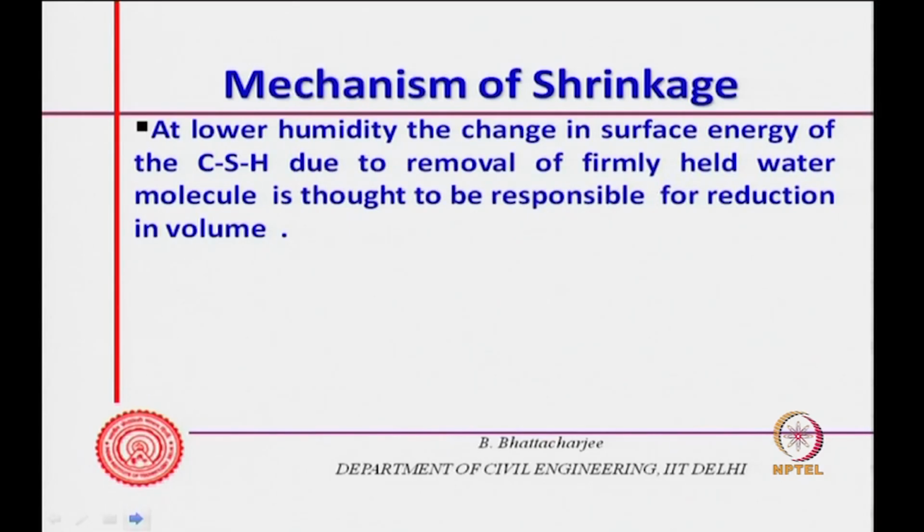At lower humidity, of course, change in surface energy of the CSH due to removal of firmly adsorbed water molecules is thought to be responsible for reduction of volume.